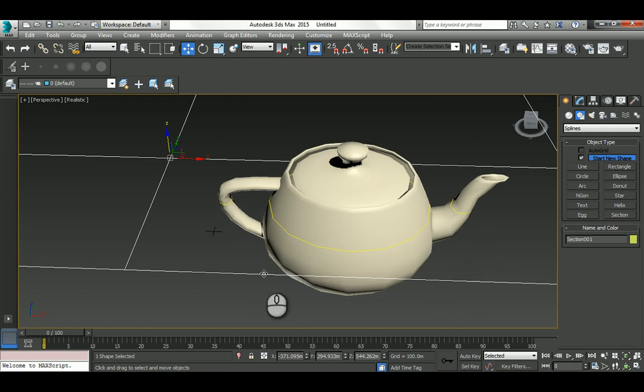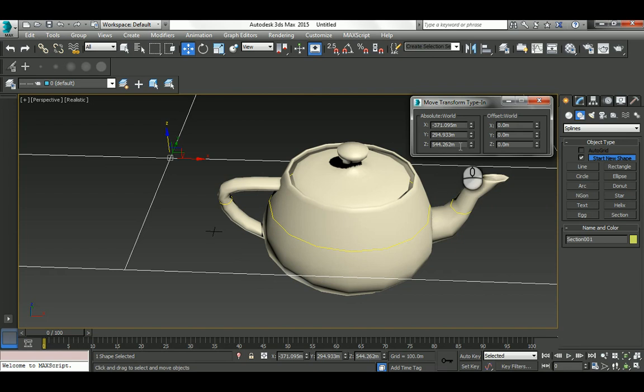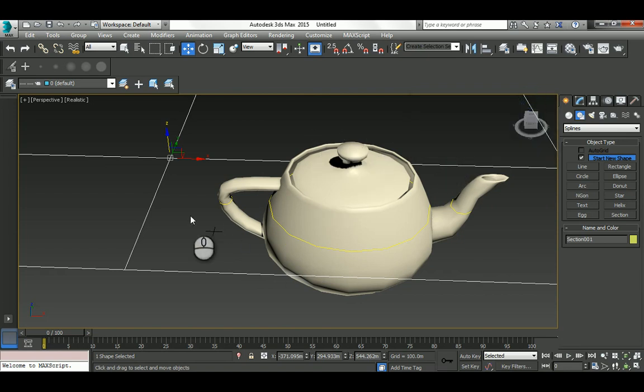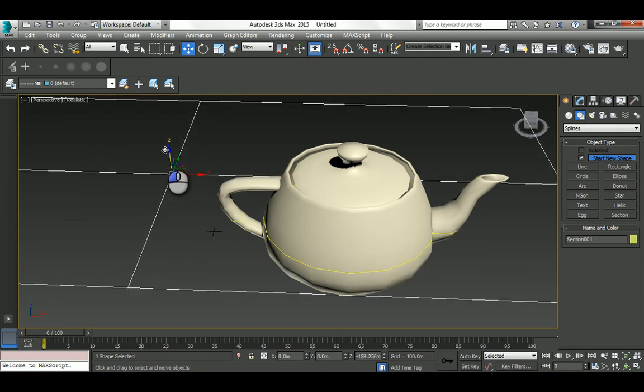So if this is a building and I want to cut that shape of it to get my plan, I have to specify the height, based on 1.1 or 1.2 or 1, whatever you want for the height for the plan. It's going to cut the plan horizontally. So the section command, if placed horizontally here, is going to create a plan for me, or you can rotate that by 90 degrees and it's going to create sections for your architectural section, I mean.